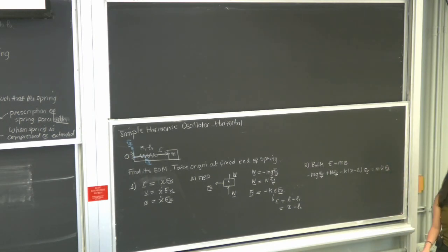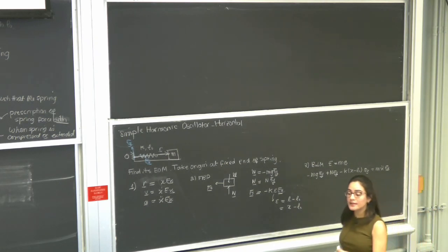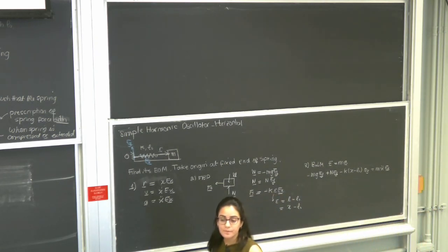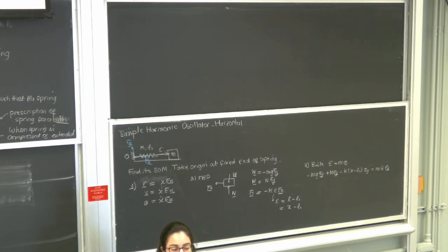How many equations of motion am I going to get in this problem? How many degrees of freedom does this system have? How many independent coordinates do I need to express the location of the mass m? Is it 1 or is it 2? But be careful, m is moving on a straight line. It's rectilinear motion.